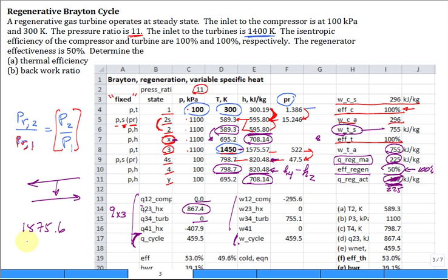H3 is 1575.6 minus HX 708. I'm just going to put 1 there. And now that's a 5. That's a 7. That's a 6. And this is, what is it, an 8? 867.5. Check. So it is Q from X to 3, which is H3 minus HX. That's how much heat goes in. Nothing for the turbine, and then for the heat exchanger.